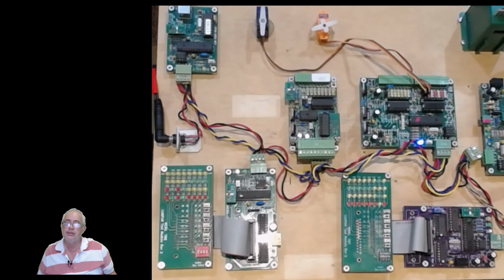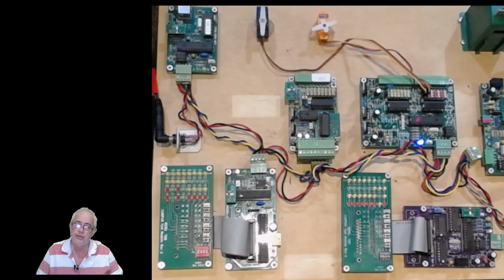Now, there's a couple of things in here. Same sort of stuff as we talked about before. If I don't set some things here, then things won't happen. Switch. I better pick a switch or nothing will happen. I better pick a switch mode. I don't want to set any LEDs on and off. If I click that, I'll get the dialog for all the LEDs there. I don't want that. I'd still have to click that to make the LEDs work. Don't want it. Send short event.